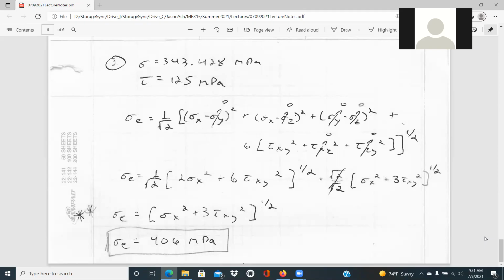And so the process that I've recommended, I call it the accounting method for combined loading analysis. Basically, make a table of all your potential stress components, then look at critical locations where those are likely to combine to generate a worst case scenario, and determine what components of stress are caused at each of those locations. Then you're able to simply add and subtract like components.